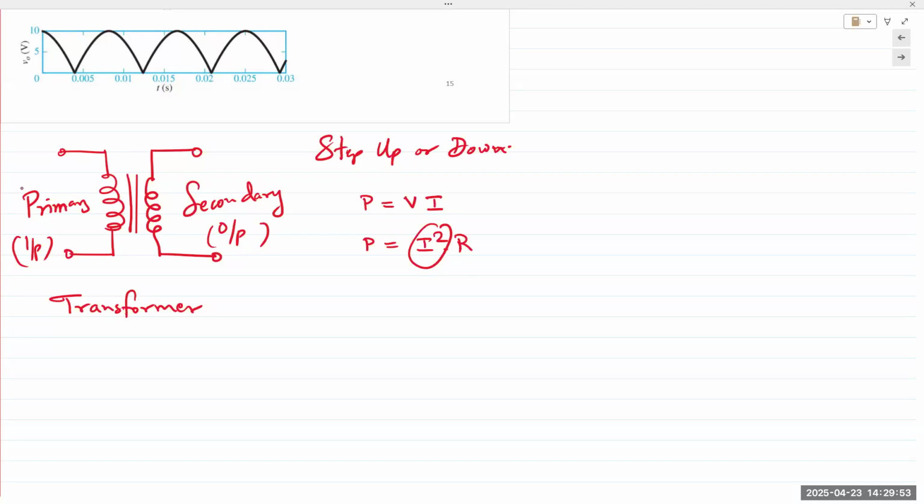As they get closer to a city, that voltage is now stepped down to what is required. So that 30,000 volts is stepped down to perhaps 5,000 to 1,000 volts. There's a substation. Even on campus, there is a distribution facility, and then power is stepped down to hundreds of volts. If you go around campus, you'll sometimes see wooden fences. It will not have a gate, or if there's a gate, it says do not enter, do not touch anything, or some kind of notice. Those have transformers behind them. Those transformers are huge. They step down the voltages, and the power is sent to the buildings.